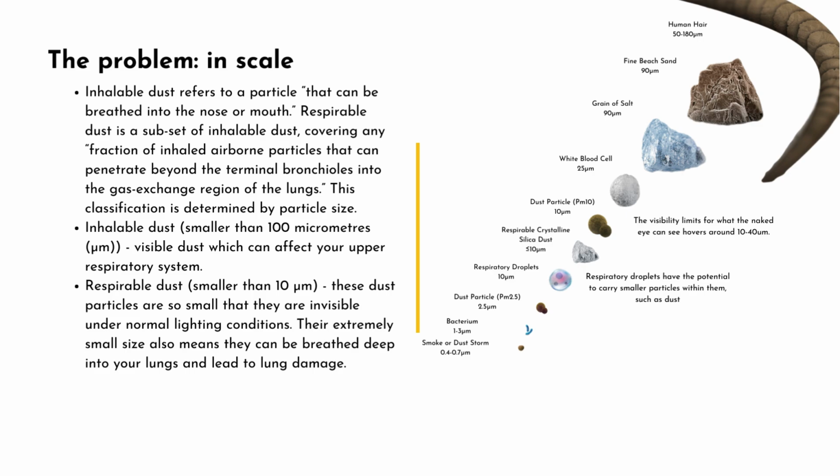The types of dust that we generally see in our industry can range from 0.01 micrometers up to 1,000 micrometers. It just depends on the product that is being loaded. Dust particles from products like fertilizers, limestone and silica sand can be tiny, ranging anywhere from 0.01 micrometers up to 10 micrometers, whereas dust from products like soybean or wheat can be anywhere from 13 to 15 micrometers, depending on its format. Basically, no matter which type or size of dust, it's bad for you, so the goal is to minimize it as much as we possibly can without impacting production or workflow.